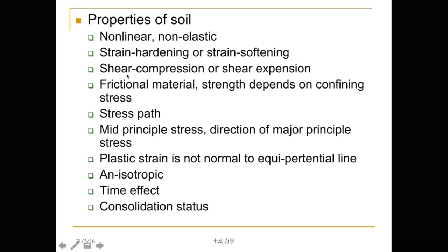That's shear compression. Or for the dense sand, with the development of the shear load, the volume of dense sand will increase. That means it tends to become loose. Then we define it as shear expansion.